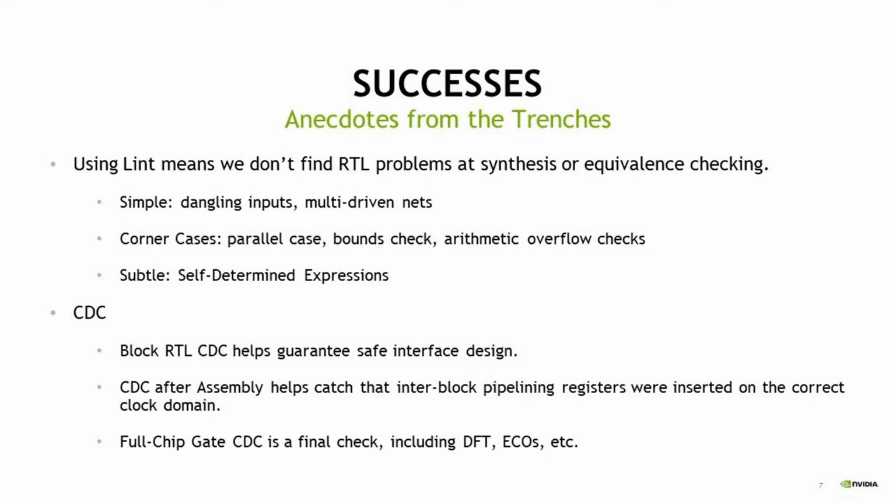Perhaps in this example, we've inserted pipelining registers in our design, and perhaps that was done by an in-house tool. And we want to make sure that those registers are clocked correctly. So the CDC would catch that at that point. And finally, why do you run it at gate level? Well, again, things happen during the design closure process. There may be more DFT logic going in. There's ECOs that are changing timing or function. And so a final check is done at gate level before sign-off.